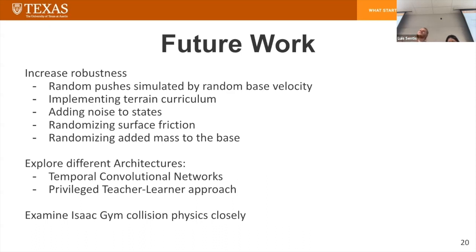And another thing that's really important: even in that actor critic kind of workflow, one thing that saw a lot of success as well is giving the critic privileged information. So ground truth basically from the simulator, stuff that it's not supposed to know. What happens when you have that kind of teacher learner thing is your learner network is able to implicitly build a model of state estimation because it's imitating something that knows what's happening. And so it's able to figure out what it needs to do without that information. Then when it gets out in the real world, it doesn't have it, but it's learned a really nice estimation that's robust. So that's something also interesting.